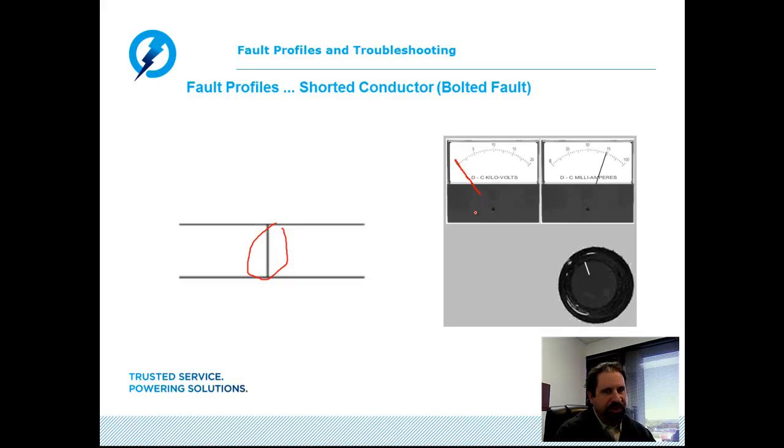Even for a short period of time, the cable will not sustain any level of voltage because we already have a constant current loop established. So as we try to bring up any potential, all we will see is just a steady rise to leakage current, pure resistive current flowing through the short circuit, and the voltmeter will not sustain any voltage whatsoever.